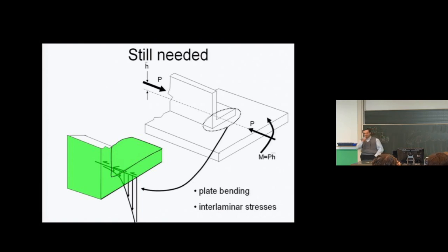And as we said many times in previous lectures, the resin, which is the only connection between the stiffener flange and the skin, being the weakest spot, will most likely fail or has a tendency to fail. So the final aspects of this design would actually require determination of these stresses and the tendency to create a delamination or failure of the matrix in between the stiffener and the skin. But the purpose of this exercise